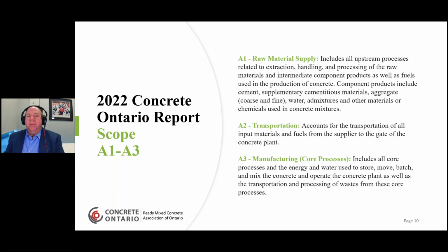At the concrete plant, depending on your performance requirements for the concrete, the producer is going to come up with an individual mix design that'll be used to meet both the hardened and plastic properties specified by both the owner and the contractor. We blend the individual raw materials at the plant. We need to proportion them either by weight or by volume, and then mix them, typically in a ready mix truck, but we also have wet batch plants and volumetric concrete trucks. So there are lots of different options or types of equipment that we can use.